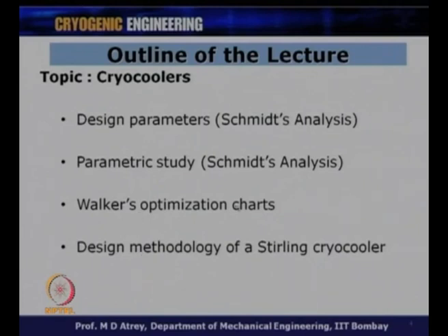And finally, using Schmidt's analysis and Walker's design charts, we will have a design methodology for a Stirling cryocooler, and this would give us a first guess of dimensions for any cryocooler to be designed for a given cooling capacity. All right.